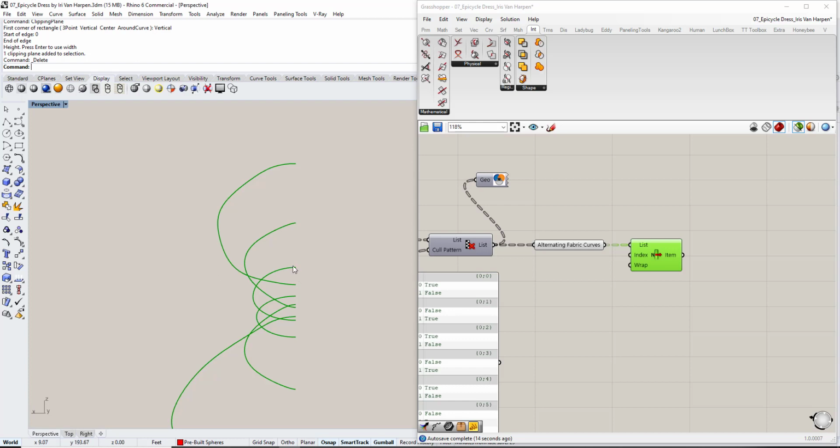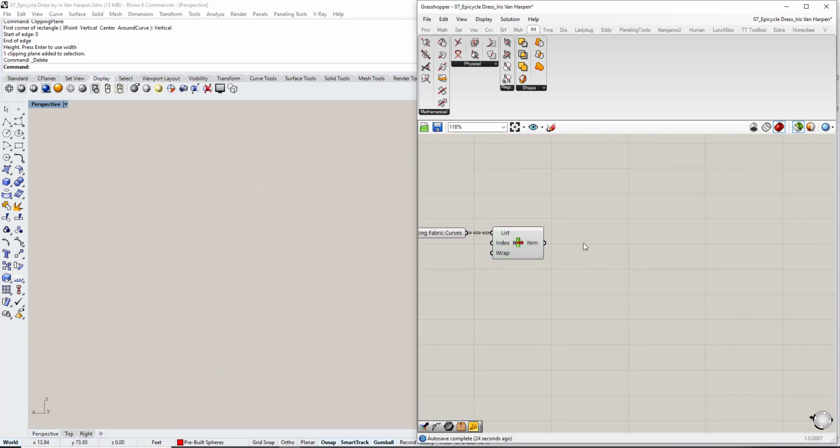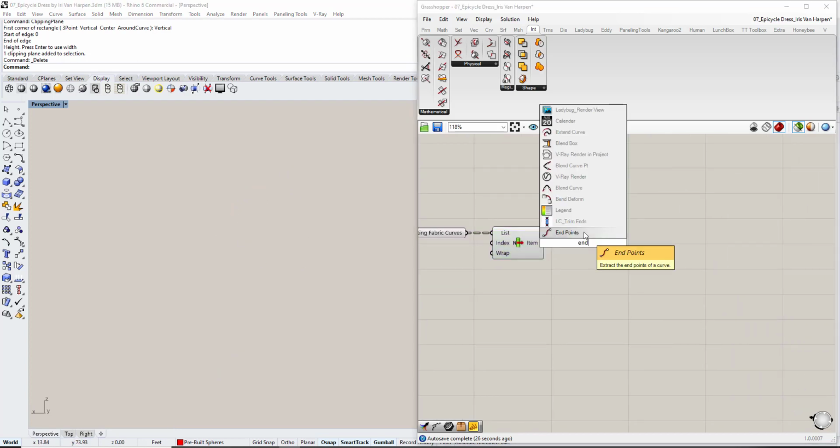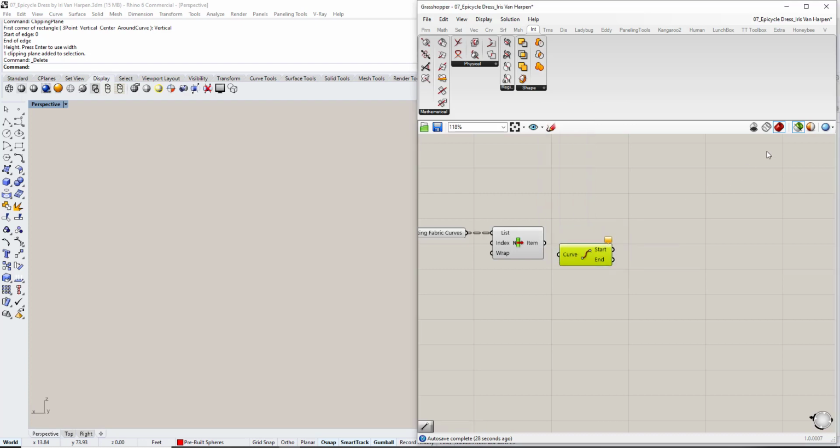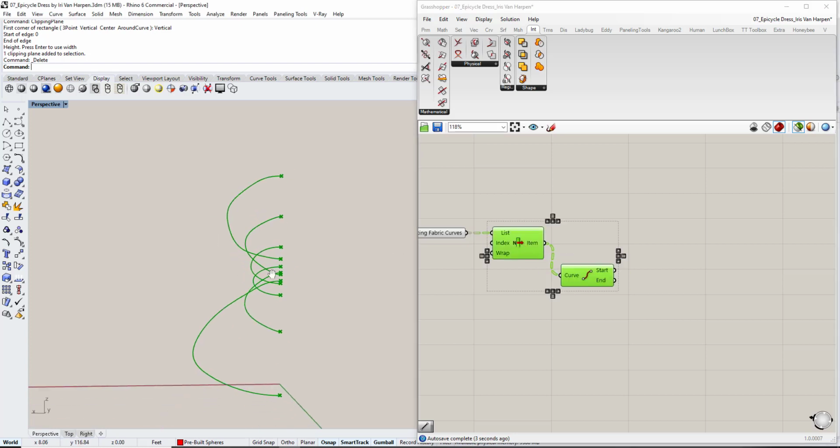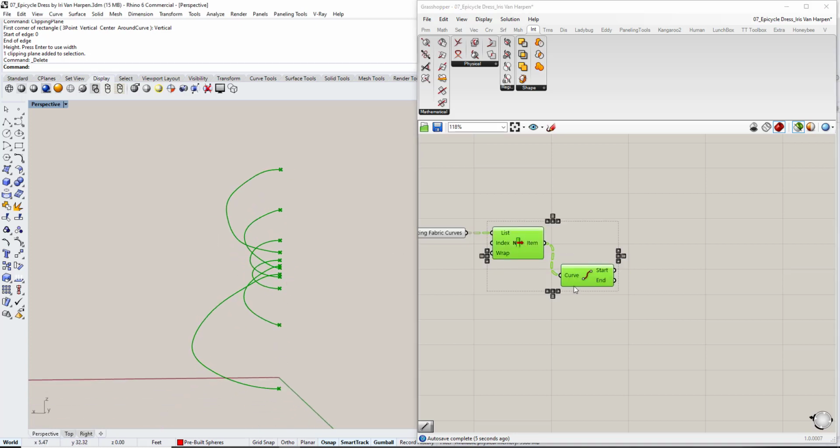So the way I can close this curve is if I figure out where the curve starts and where the curve ends and draw a straight line in between them, I should be able to close them off and create a surface. So let's go ahead and try doing that. So grab the endpoints. Actually, let's just work on this one, right? So if I hold down Shift, I can see both of these, and I can see that I've grabbed the endpoints.